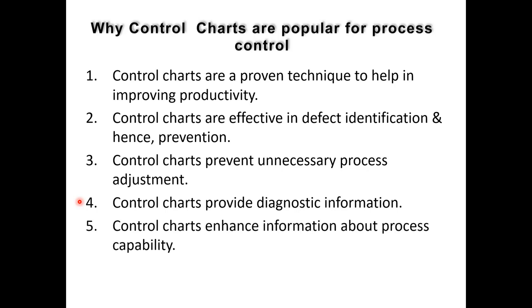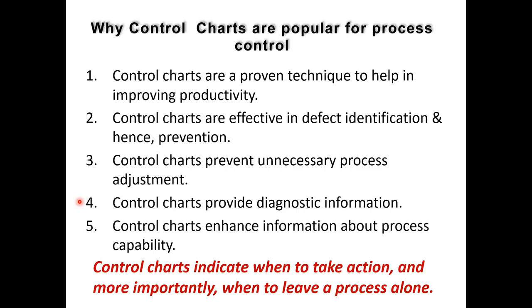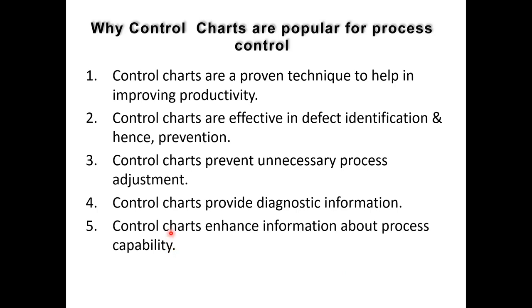Control charts enhance information about process capability. By having looked at the stability of your process, you can further study the process capability. This is very important because these two, process stability and process capability, are not the same. They are two different things. So the control chart tells you process stability. Then you will study the process capability.